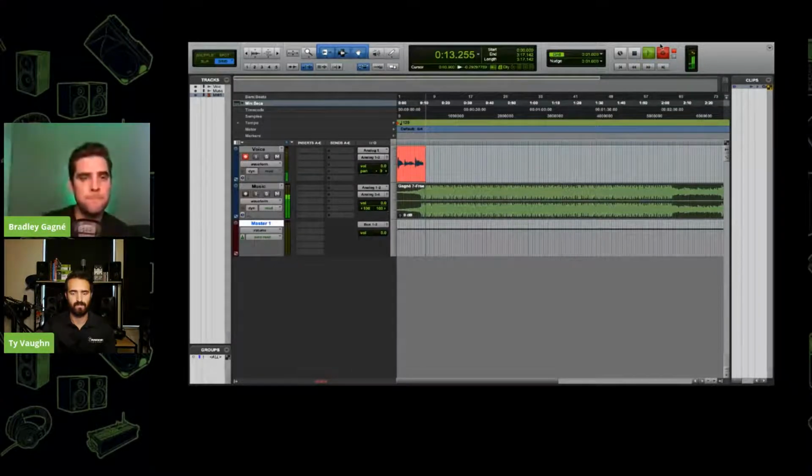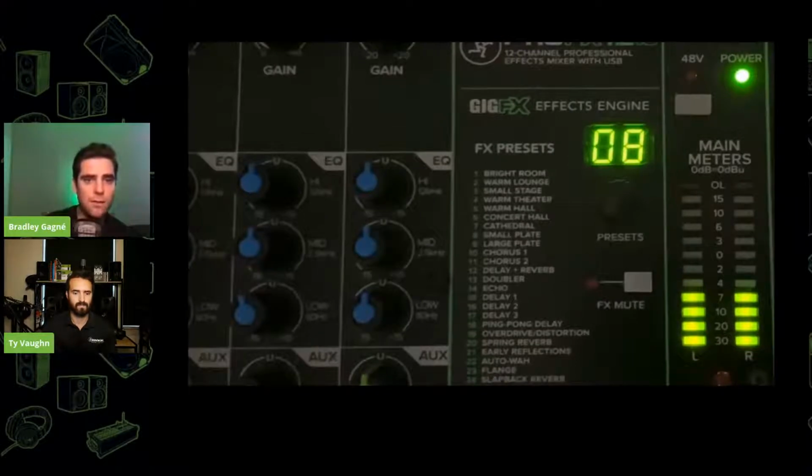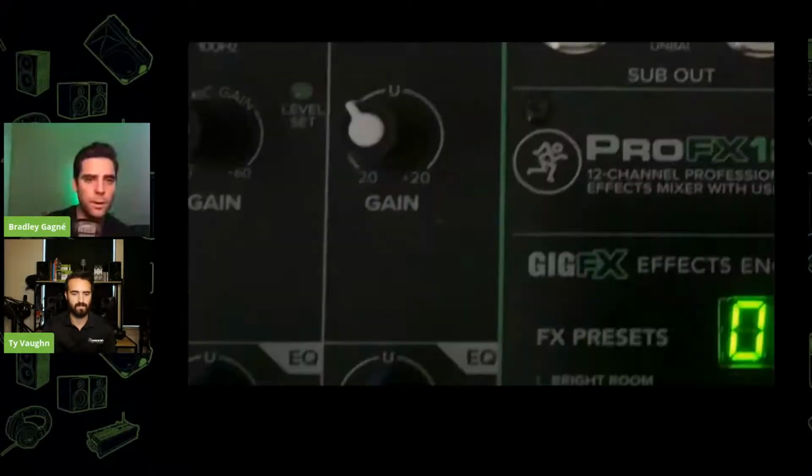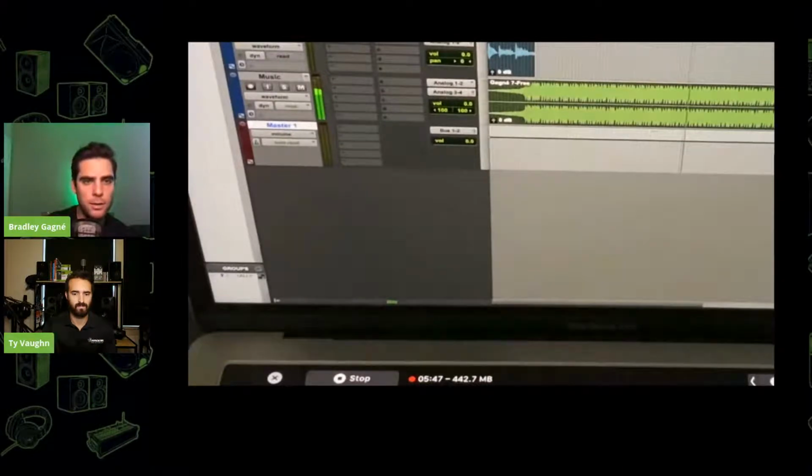And that's how you get sound from an analog mixer that has an audio interface built right in. And then you can see that I've routed audio 3-4 back onto my mixer. I just push that button there. And then inside my DAW right there, that's the audio being routed 3-4 output back onto the mixer. So if I have my theme song or if I've got sound effects, I can route that out of output 3-4 from your DAW, and that's going to go back onto the mixer. So I can control the level with the fader.